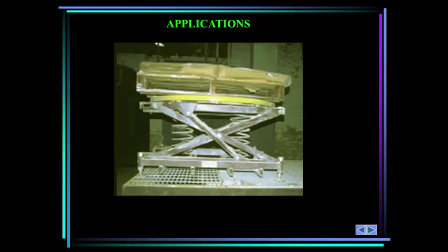So here's an application. The weight of these sacks compresses these springs and stores potential energy in them. As you remove these sacks, the platform will slightly rise, since some of the potential energy in the springs will be transformed into an increase in gravitational potential energy of the sacks. If the sacks weigh 100 pounds, and the spring constant is 500 pounds per foot, what is the energy stored in the springs?